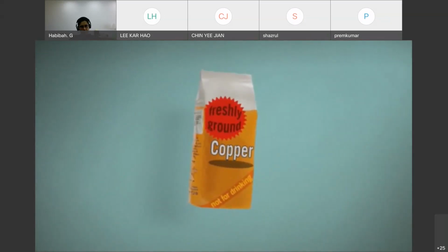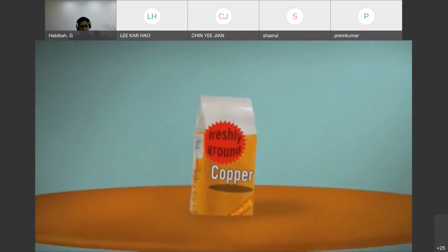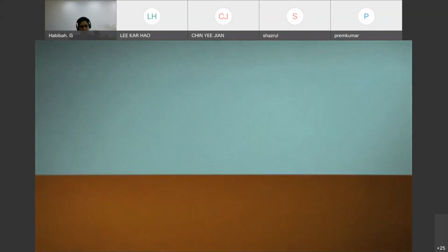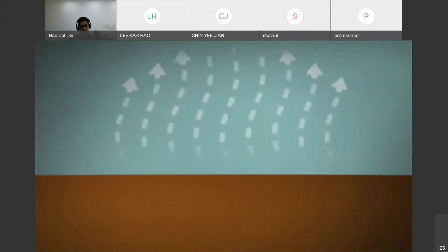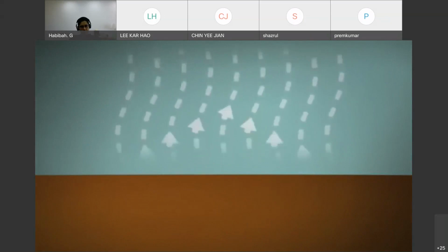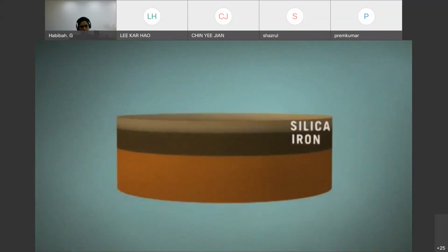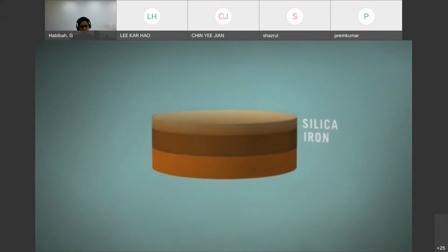This powder goes into a large, very hot flash furnace, which causes the dried concentrate to melt and turn into a molten metal called matte copper. During this process, sulfur gases burn off and are then captured and cleaned. A combination of iron and silica rises to the top, and the heavier copper matte sinks to the bottom.